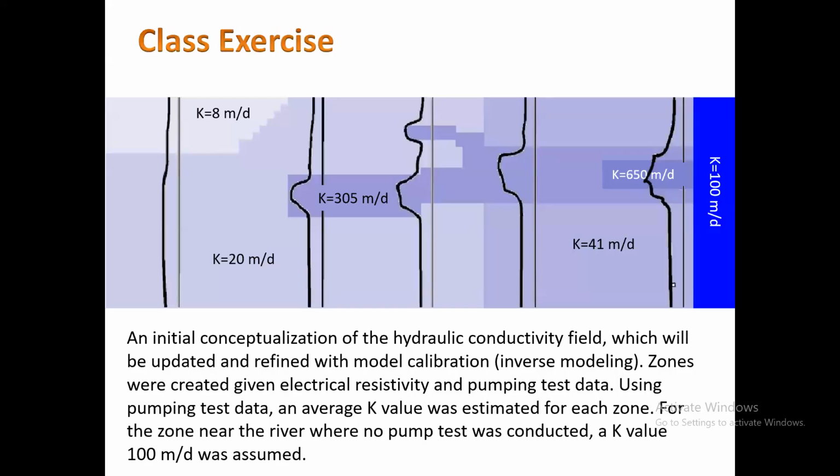Okay. But this equation is missing something. What it is missing is what is happening at the boundary of my system, right? Because H will depend on what's happening at the boundary. Is water flowing out of here, or coming in from here? Water flowing out will affect my H. Do I have recharge happening on the top? That will affect my H, right?